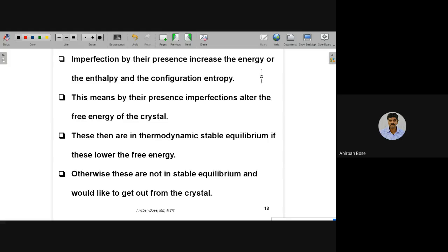If this is one of the atoms at the surface, it is connected with another atom here, but it is supposed to be connected with another atom here; since it is the outer surface, that atom is not present, so this bond is not there. Corresponding to that bond, half of the bond energy will increase, which means the energy of this atom will be higher. So this is not exactly at its most stable state.